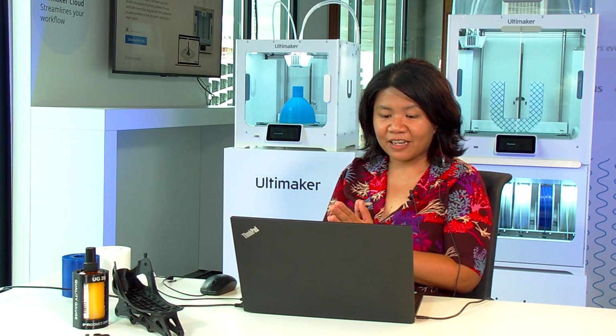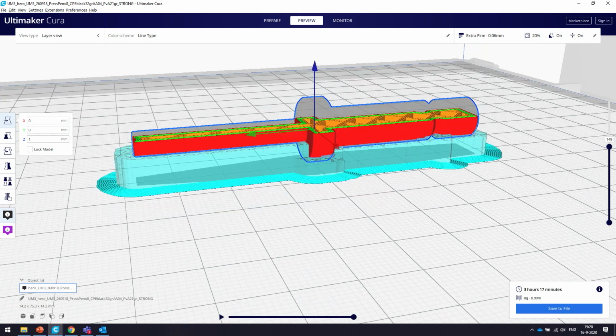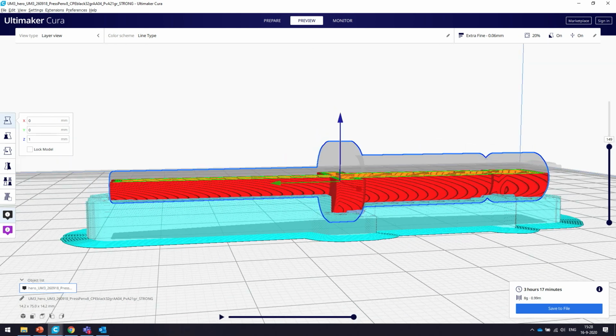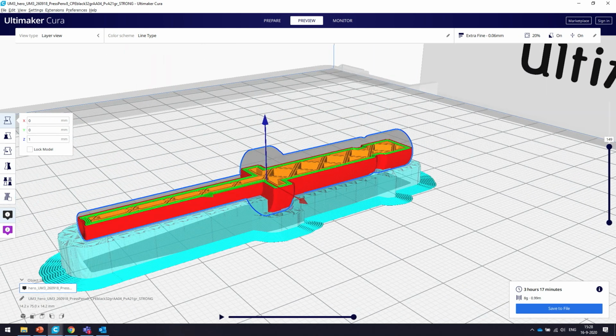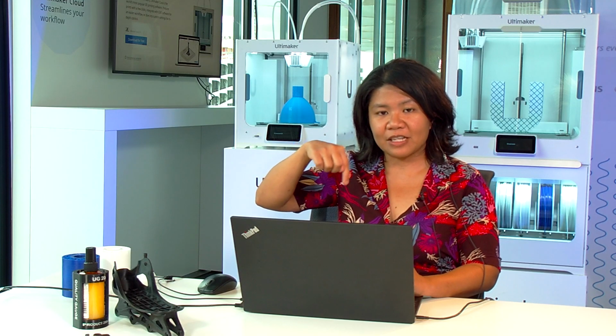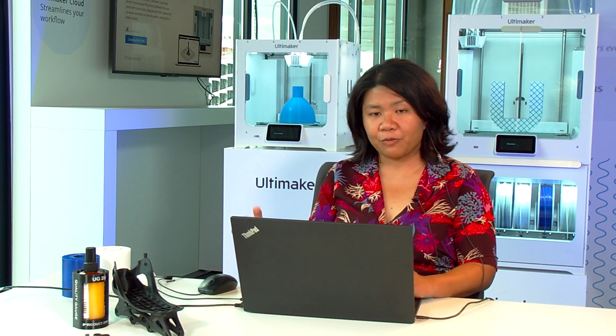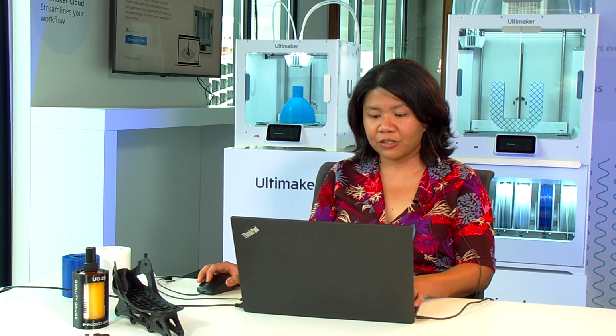Our Z position is 1 because we want to put support underneath, because we want to keep this shape underneath it. It is also laid down horizontally because if we print this standing up, it's not going to be that strong, because when we lay the layers down, it is vertical. I will talk more about that later when we go through the orientation.